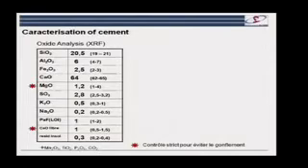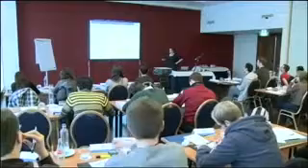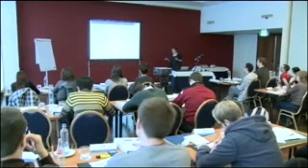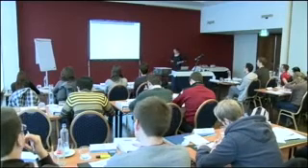The ones that we've got to control are particularly the amount of magnesia, because if we have too much magnesia, this will cause swelling. Sorry, I didn't translate this from French. That means strict control to avoid swelling. We also have to control the amount of calcium oxide, which is not combined as other phases. So free lime basically means not combined in other solids.